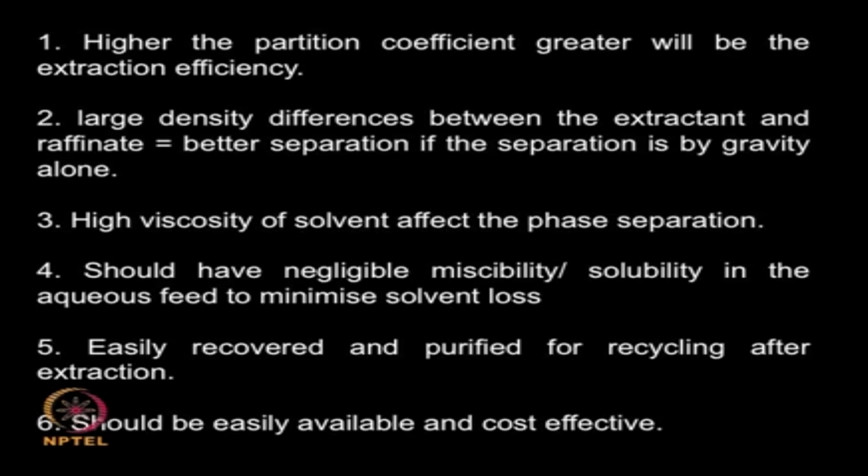Now you should be able to remove the solvent from the solute after the extraction, because your solvent has to be purified and again recycled for further extraction, because the cost plays a very important role in your downstream, and the solvent recoverability is a main issue in the overall operating cost. The solvent should be easily available, we do not want to use many exotic solvents because then it may be very expensive and it will add to the extraction cost.